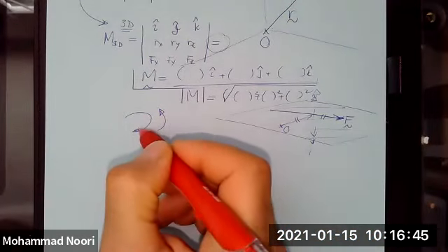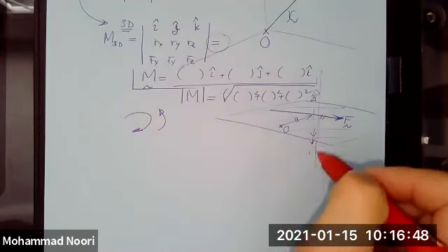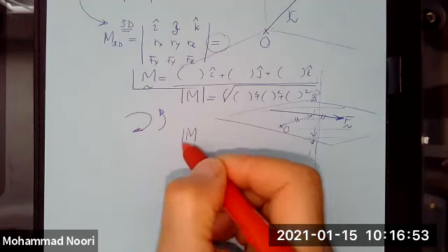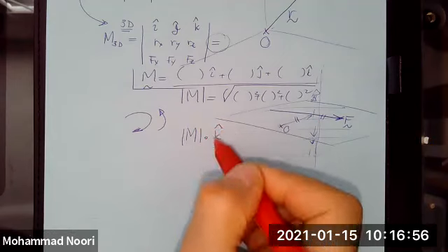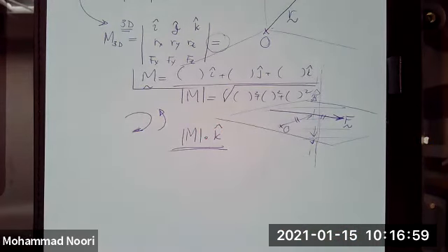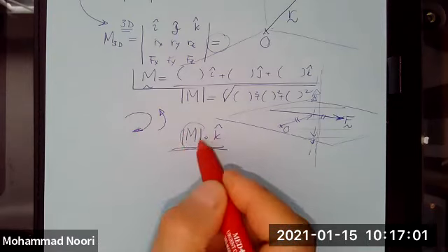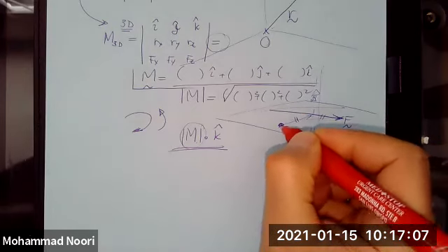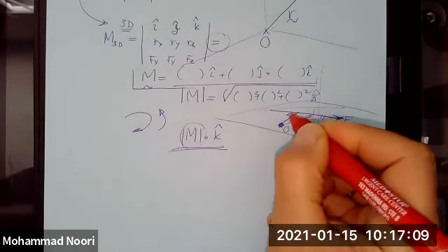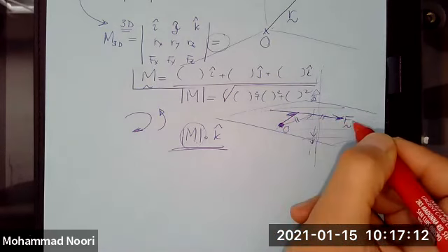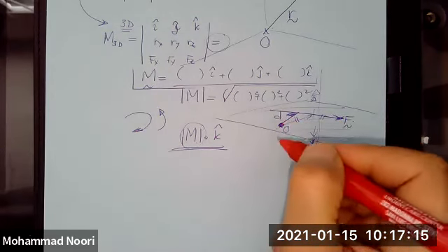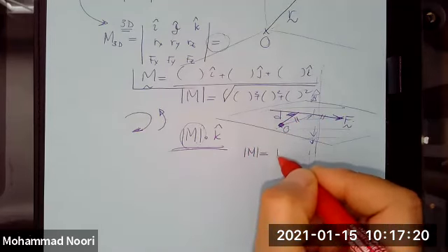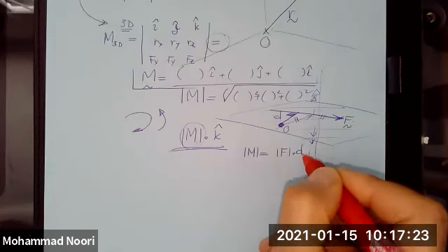We forget about that in 2D. We say, since it's always along this direction, a moment in 2D always has a vector equation which would be this, okay? All we care about is the sign of this. And the sign of that can be determined this way. If you have this point, you just simply draw a line perpendicular to the direction of the force. So you find the perpendicular distance, and the magnitude of this moment would be the magnitude of the force times that distance.